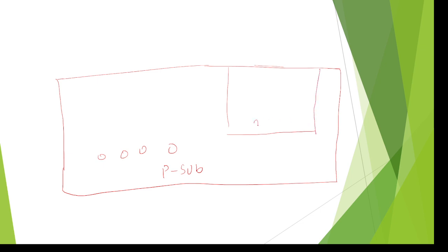That diffused region is named the N well. Then to design gate terminals, deposit the polysilicon material at the middle of the substrate. The oxidation process is common, so I am not drawing it here. So this is a gate terminal, gate 1, and this is one more gate for the right side transistor.